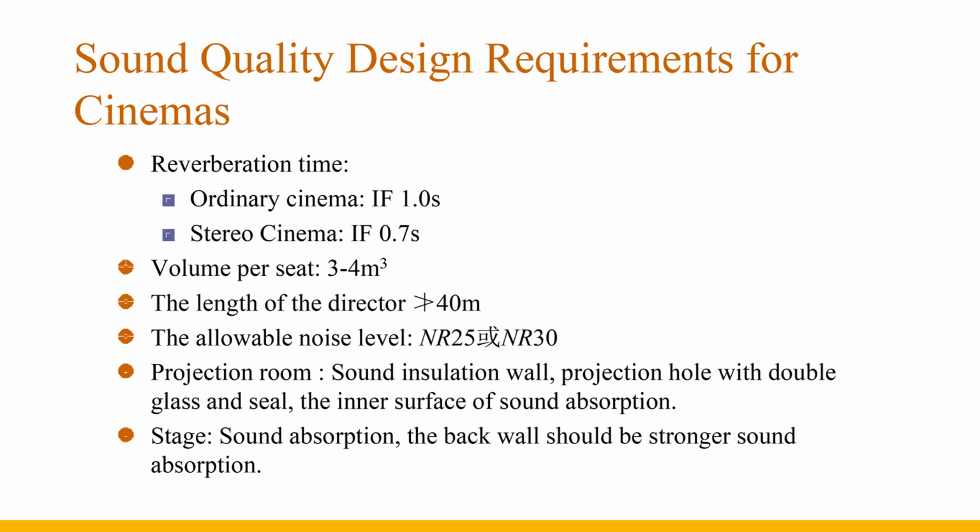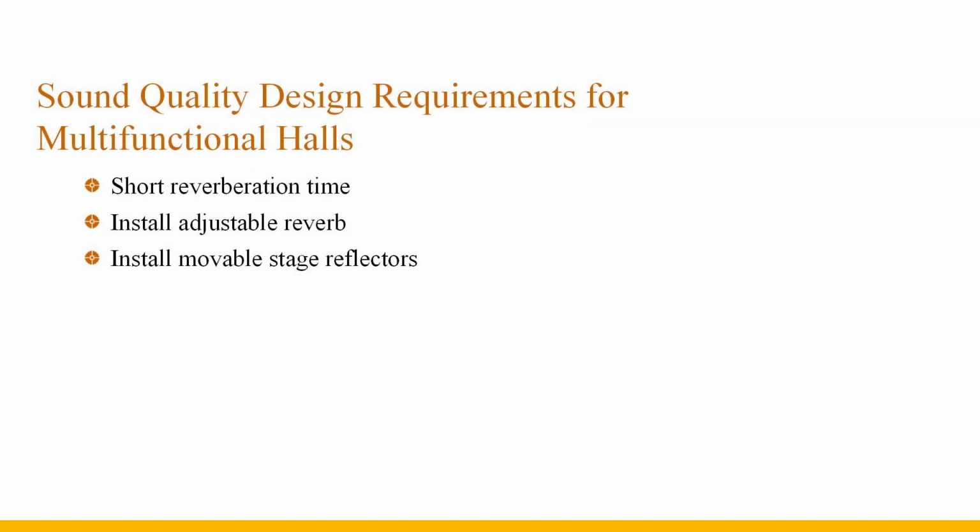The projection hall should be sealed with double-layer glass, and the inner surface should be sound-absorbing. The small stage near the screen needs to be sound-absorbing, and the back wall should be given strong sound-absorbing treatment to avoid its reverberation time being longer than that of the auditorium.